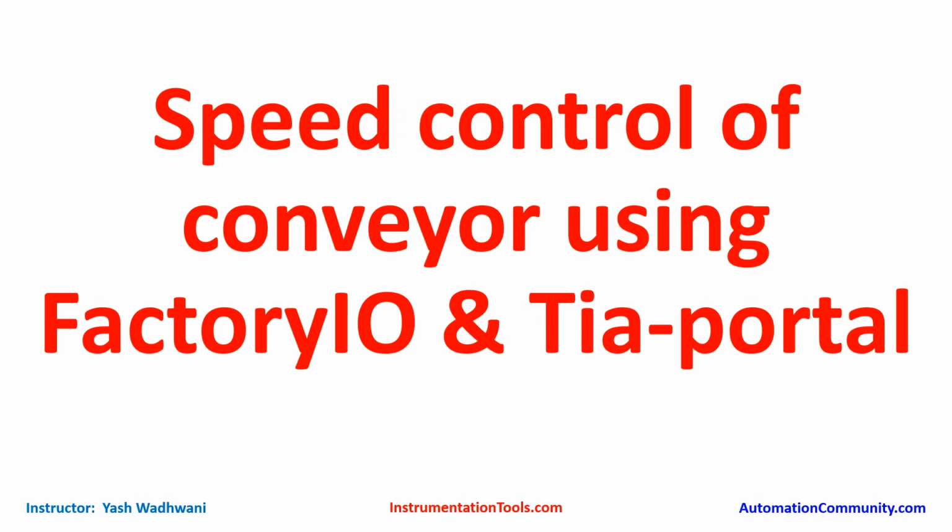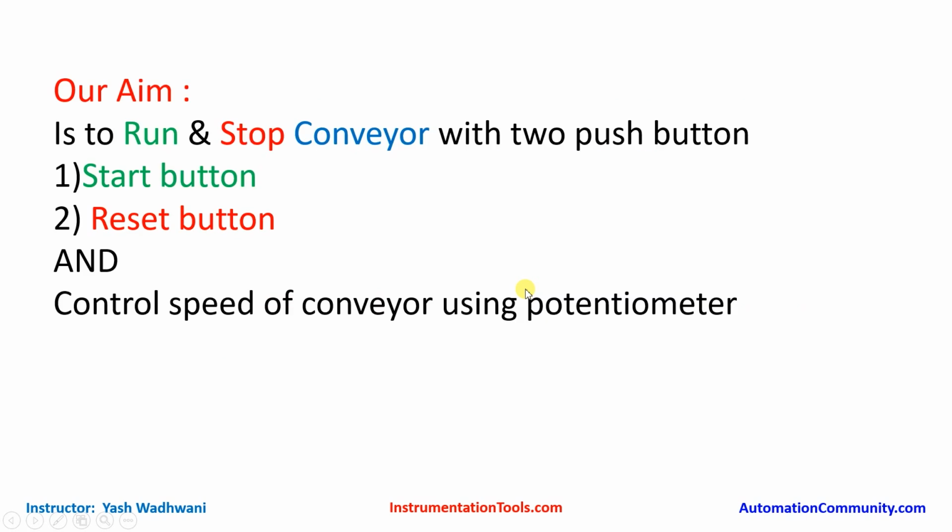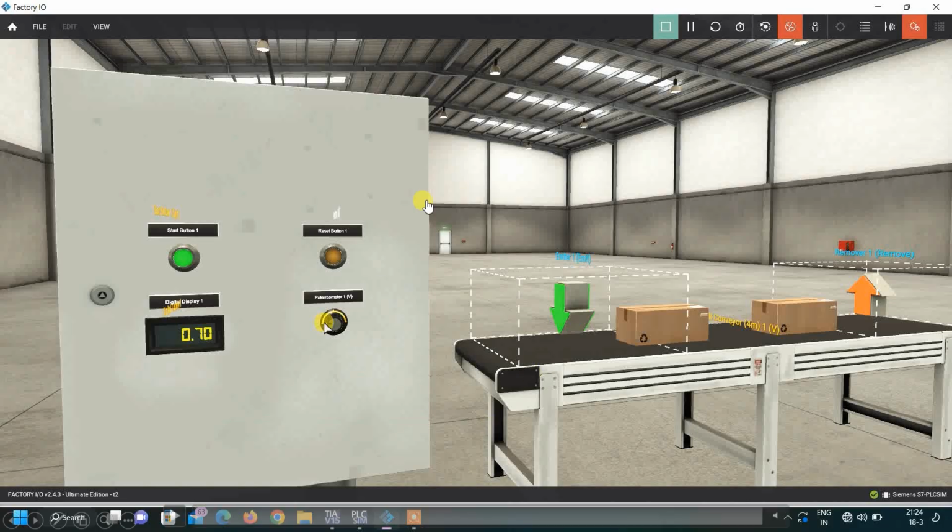In the previous video, we have already seen how to link Factory IO with Siemens TIA Portal. So from this video, we are going to start our first example, that is speed control of conveyor using Factory IO and TIA Portal, because without using any hardware, we are going to do simulation. So our aim is to run and stop the conveyor with two push buttons, that are start button and reset button, and also we want to control the speed of conveyor using potentiometer. So exactly the idea will be clear to you after watching this video.